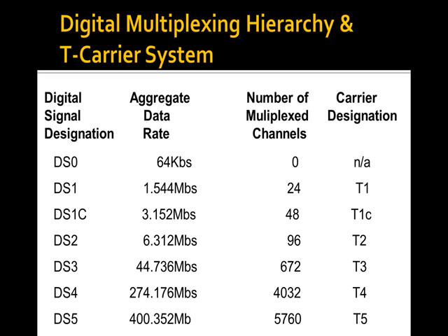If you look at the numbers, we've taken 24 DS0s, that's 24 individual conversations, and we've put them on an interface. A T1 interface consists of 2 pairs of wires. Okay? How many analog conversations can I move across 1 pair of wires? 1. So in other words, I've increased my carrying ability just with 1 level of multiplexing. I've increased my carrying ability by a factor of 12. Pretty impressive.